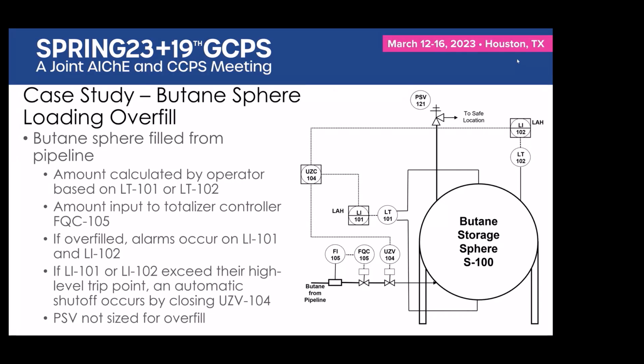So even in the 61511 standard, it recommends that if your LOPA risk assessment isn't achieving reasonable results, you should be doing something more sophisticated. So I don't really see any conflict between any standards out there and the more sophisticated fault tree approach that we're talking about here.